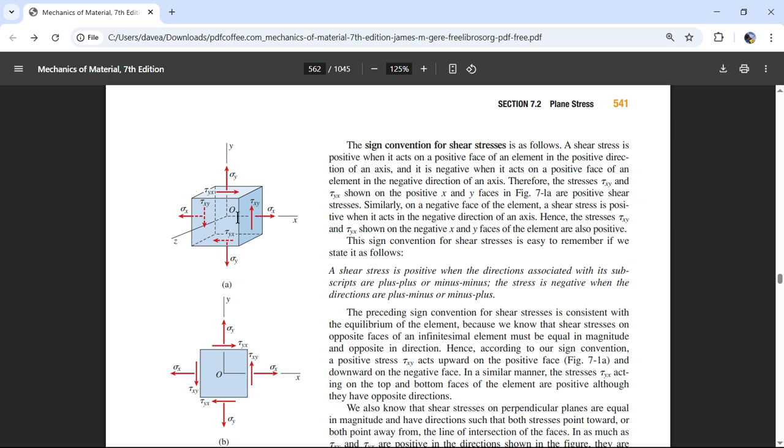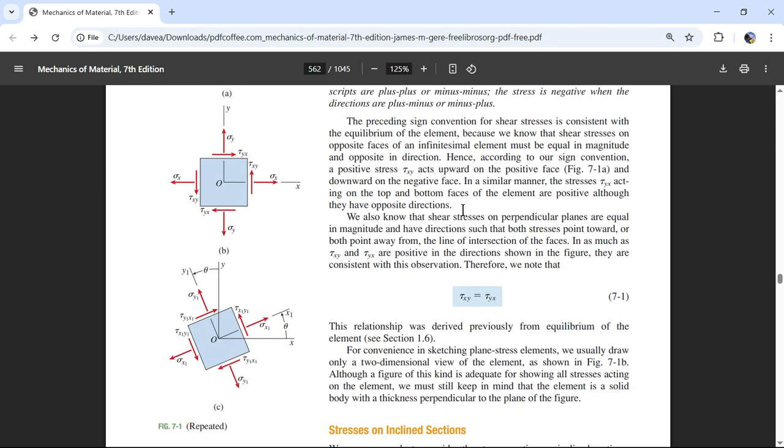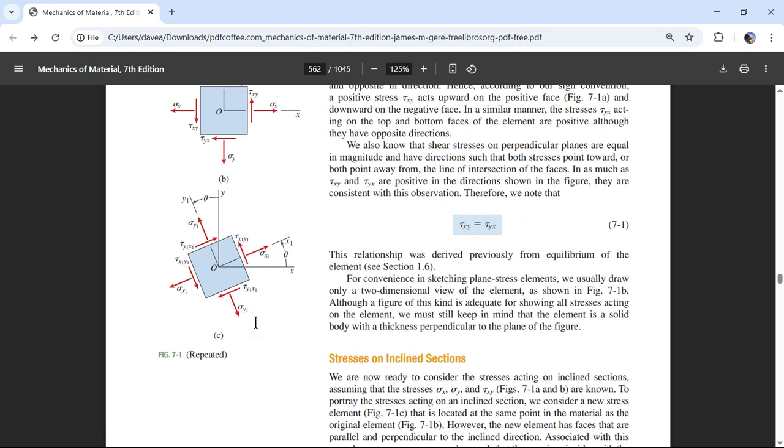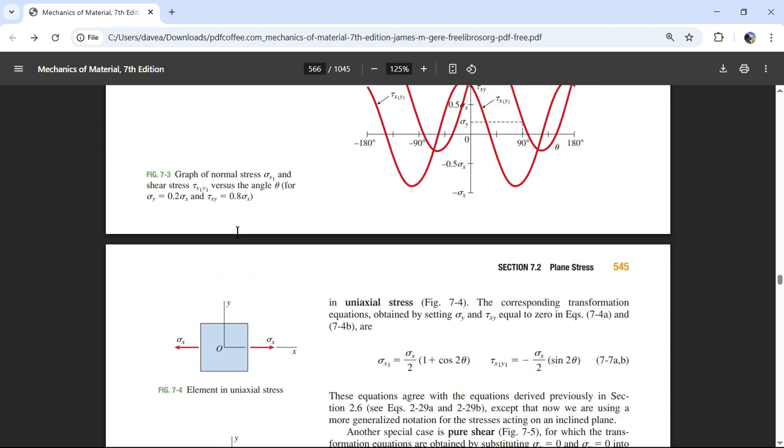So just the fact that we can take a shear force and say this shear force is very much related to a normal force in this direction, and a compressive force in this direction. And it is. This shear force is equal to those things, but we just have to orient this object at a 45-degree angle if we're going to say that. And so that's this whole chapter, taking this cube and just rotating it. And when we do rotate it, those shear forces and normal forces will vary.